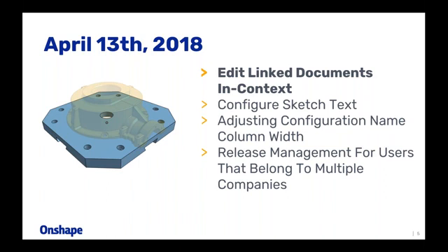So in the past, to clarify this, you were not able to insert a part, for instance, into a different document and then edit in context of that assembly that you inserted, right? That was a limitation in the past. And so it meant that if you wanted to design in context in that scenario, everything kind of had to be in the same document.